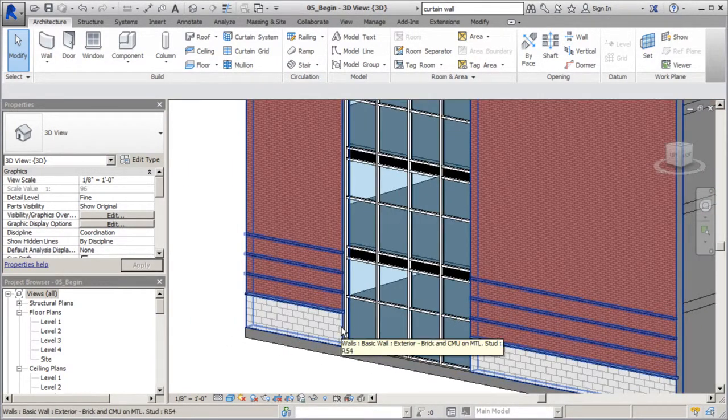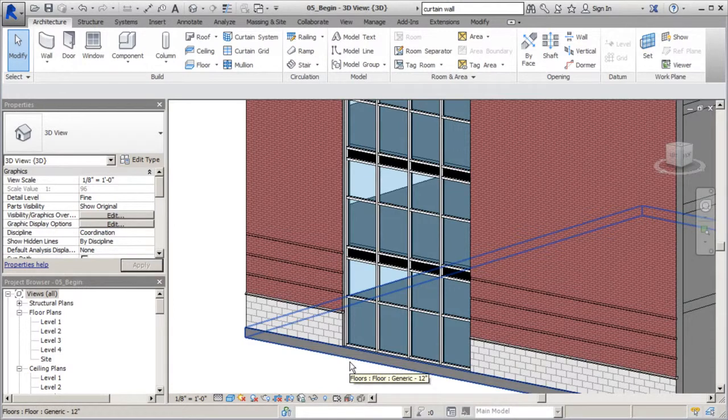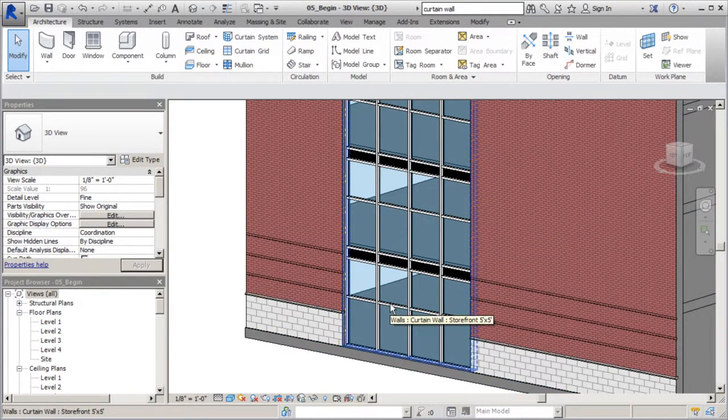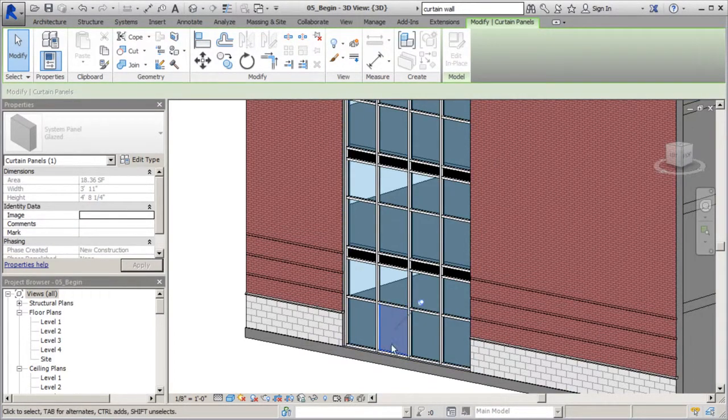To get a door in our panel, unfortunately, when we're making these, they don't automatically come with a door. That would be nice to already have, but there's a workaround for that. I'm going to highlight over the area I would like to have a door, and I'm going to tab. We're going to replace this panel with a door. That easy. But we just have to select it, unpin it.